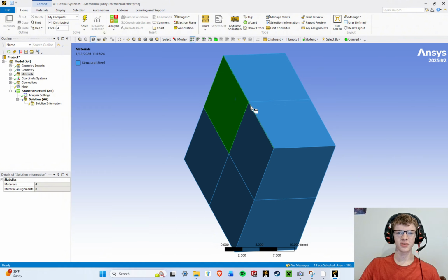If you select a point, vertex, and you hold down, it will let you continue to select only vertexes. If you want to select multiple kinds of things or multiple things, and you realize that left clicking and then left clicking another thing is not going to work, holding down Control is what you're looking for. Left click, hold down Control, and you can select multiple entities and multiple kinds of entities.